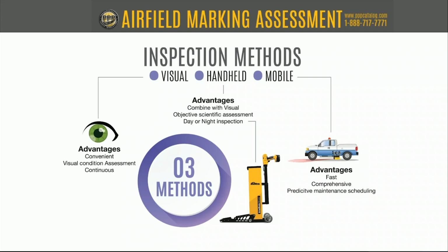And it's not even that. They'll tell you accurately how that marking is performing in that instant. It does not necessarily tell you how long that marking is going to perform that way. So for new construction, for example, you're going out and doing quality assurance testing with reflectivity, and you're following the ASTM, the FAA specification. You've got all your ducks in a row, and you're getting great readings. It doesn't tell you if it's going to be that way in 6 months or a year. It just tells you what it is today.